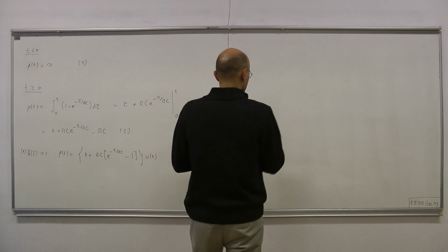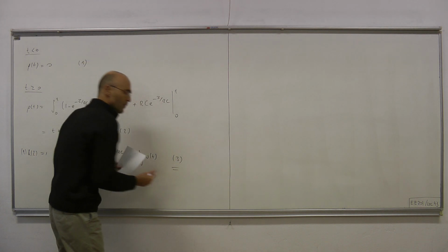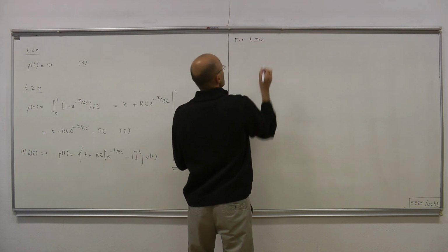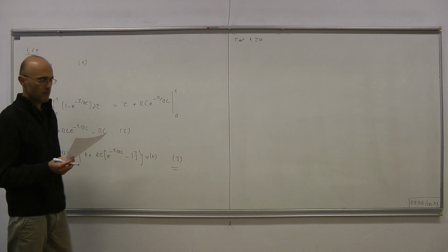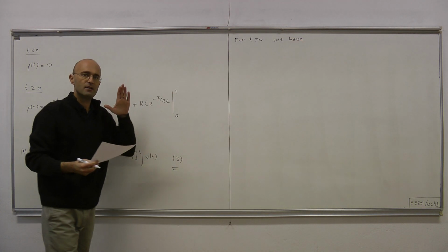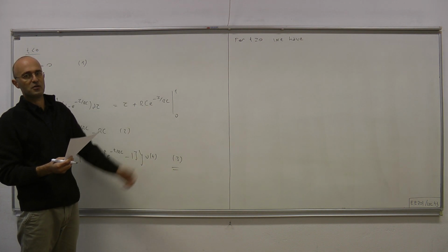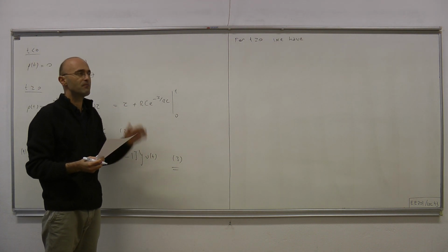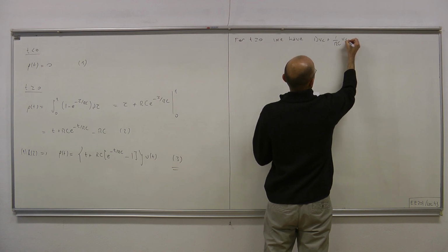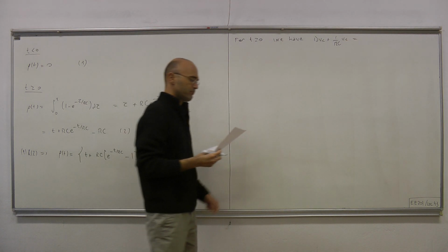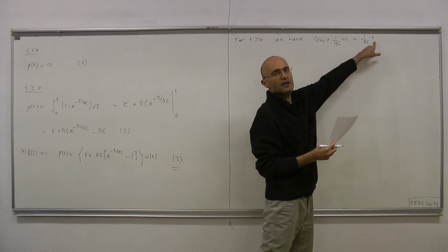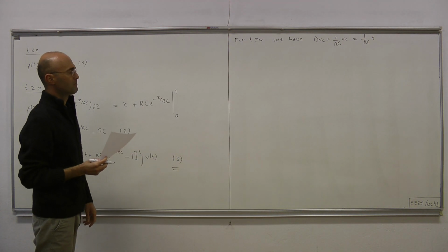Now what we're doing is verifying this equation, this time using the differential equation. For t negative, everything is 0, and for t positive, the voltage provided by the voltage source is increasing with unit slope, starting from 0. So the voltage is t. That means the right-hand side of our differential equation is t over RC, 1 over RC times t. So the input is a ramp function.